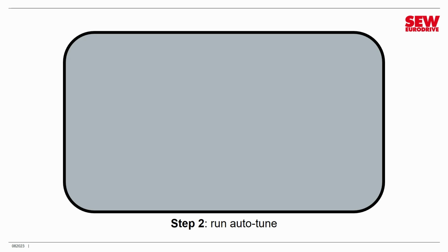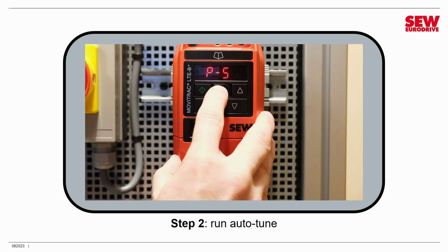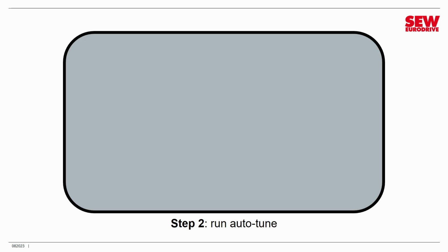We need to tune our motor. Now this is a demo unit, so it's perfectly safe if the motor runs, but I am going to just remind myself that it could run, so I'm not touching it or anything, just to be safe. I'm going to move ahead to the next parameter, parameter 52, and I'm going to put a 1 in there, and as soon as I hit navigate, the VFD is going to start tuning. So my motor will make some funny noises and it might move. I hit navigate. All right, well that is auto tuning completed.